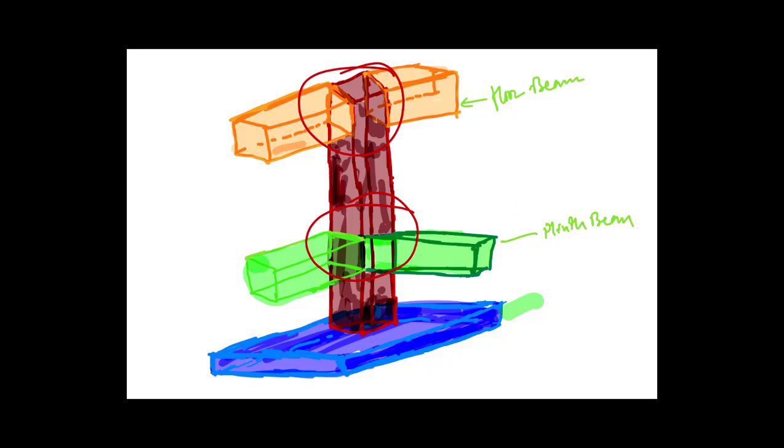In this case you may think that as there is no requirement of the shuttering here, we have to deduct that much of area. So we should look into the IS guidelines, what it says in this type of case, whether we have to deduct the shuttering area which is intersected by the beam or not.